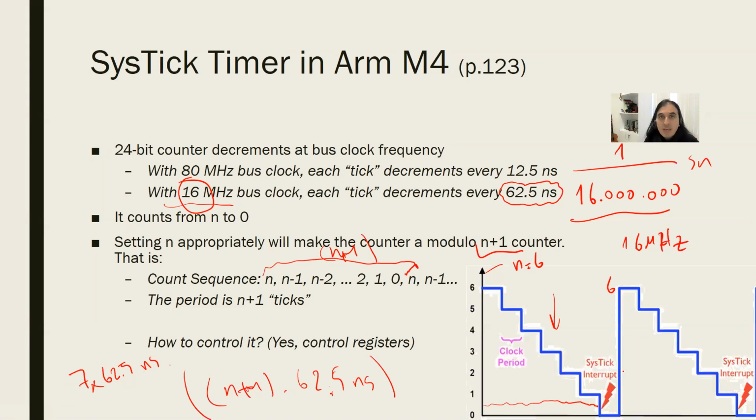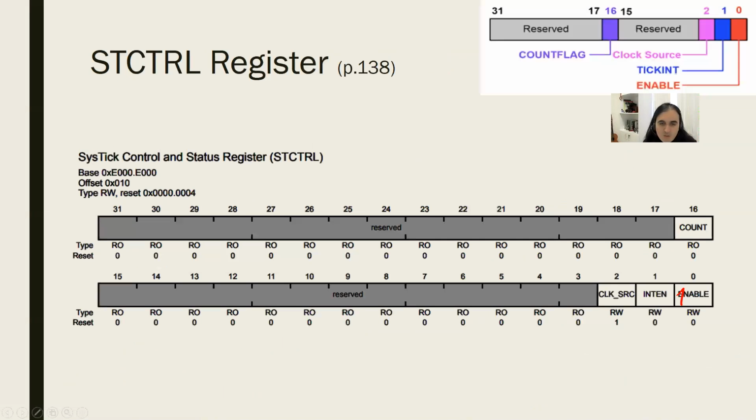The mechanism is, it comes to 0, it just does not jump back to 6 because it was the previous value. At 0, it reads the reload value. If it is changed to 8, well, it starts counting from 8, not 7. So at each hit to 0, it checks the reload value and loads it to the current value. That's the mechanism. That's how it's wired. That's the architecture. So that sentence was explaining that actually.